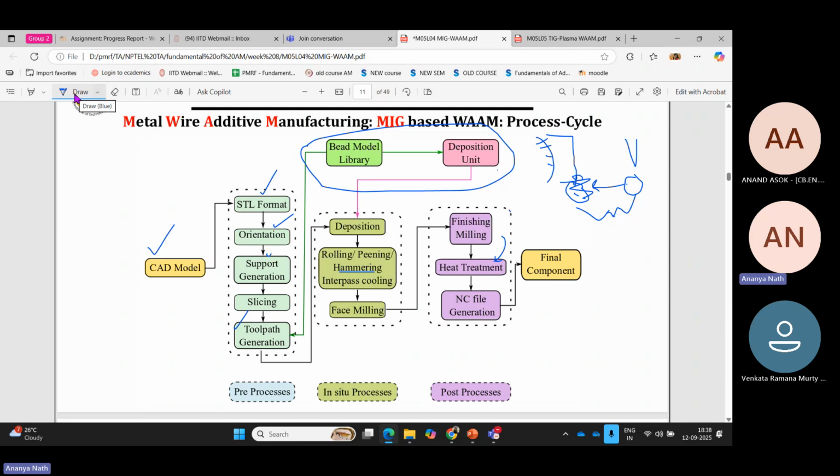And if it's 300 degrees centigrade and the argon gas is also continuously fed, it will come to 100 degrees very easily. By that time, the machine can set the part near the subtractive machine, and the subtractive tool can come down and fix the position where it will start its machining. By that time, it will reach the lower temperature. If not, then you can put some dwell time. So that's the answer.